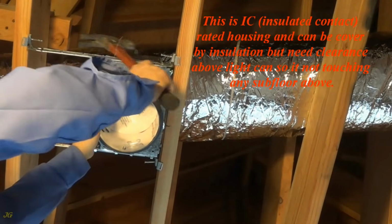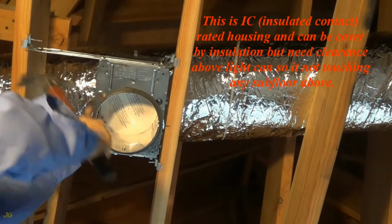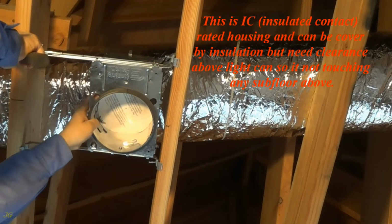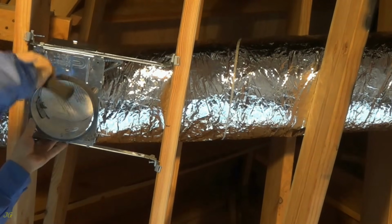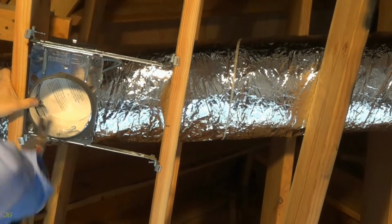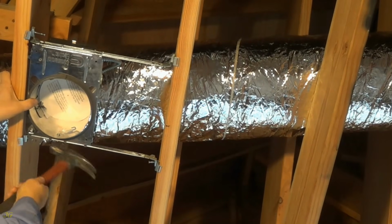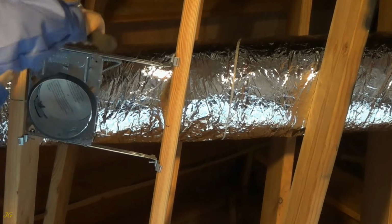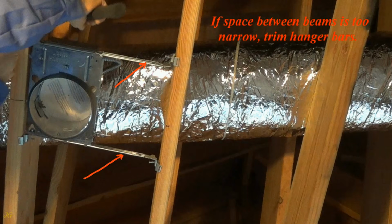This is IC, insulated contact, rated housing and can be covered by insulation but need clearance above light can so it not touching any subfloor above. If space between beams is too narrow, trim hanger bars.